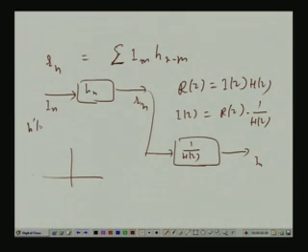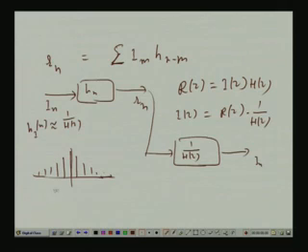So, if h I n, I for inverse, this is the inverse system, corresponds to 1 by H z, it will be stable, absolutely summable, but it will be non causal. Since it is stable and therefore absolutely summable, it will die out. Any stable system's impulse response has to die out after some time, because if it has appreciable value all along, then it is not absolutely summable, it is not stable. So, that means we can truncate it, maybe up to capital N and minus N, and beyond that we know it is already 0 or very close to 0. So, truncate it.